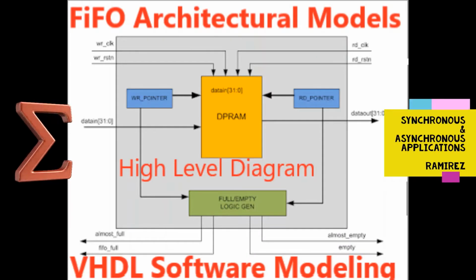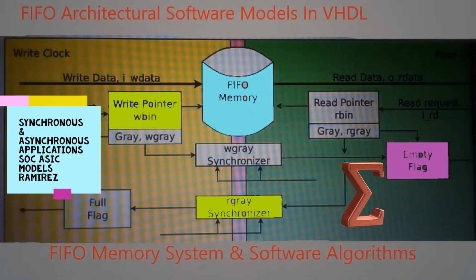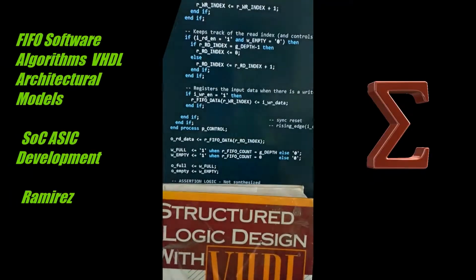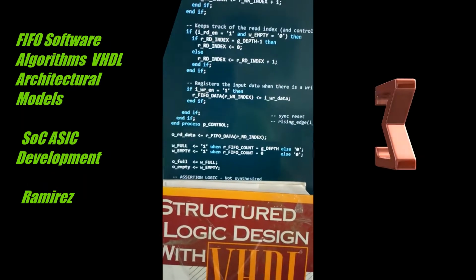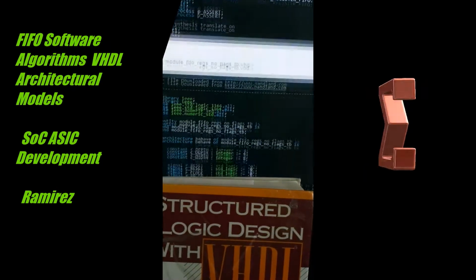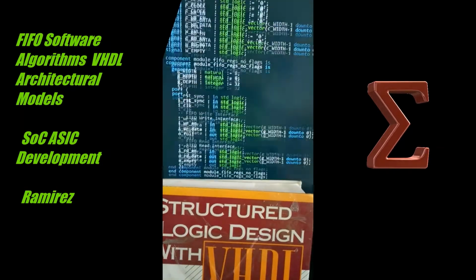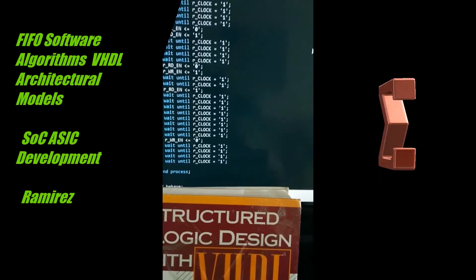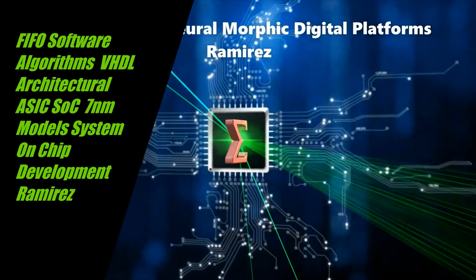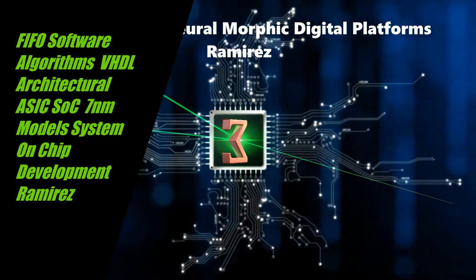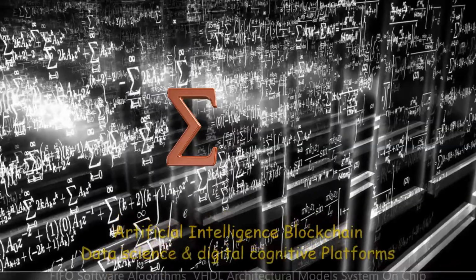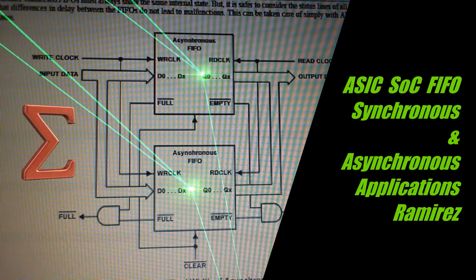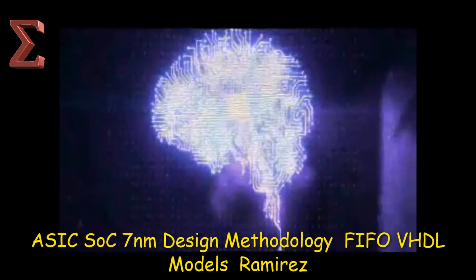When the write operation starts, after writing the first data, the FIFO empty flag is deasserted and the write pointer increments. The read pointer is still addressing the contents of the first FIFO memory word, which immediately drives that first valid word onto the FIFO data output port to be read by the receiver logic.